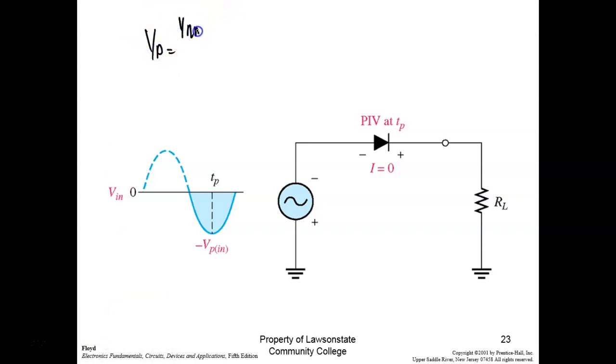Yeah, the RMS times about 1.4, and then subtract 0.7. And normally we shoot for twice, so we usually double this on our diodes. So I think I got a 4001 right here, which would be right.